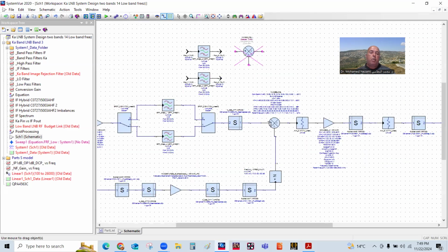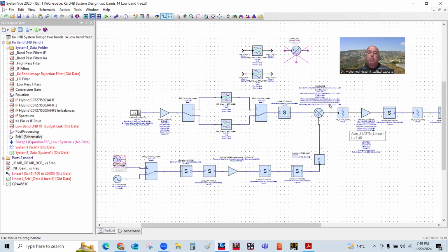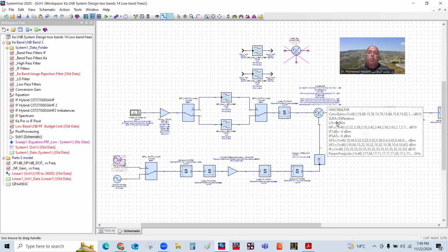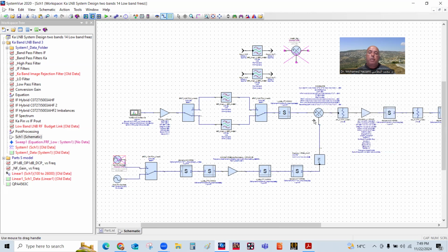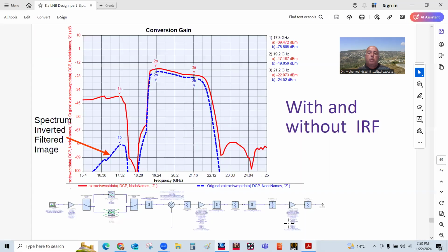As you can see now, this single sideband down converter is designed so that you can actually utilize it without a front end filter. So what I'm going to do is come in here and disable this, not as open, but as short, and then let this run through without a front end filter and see what happens.